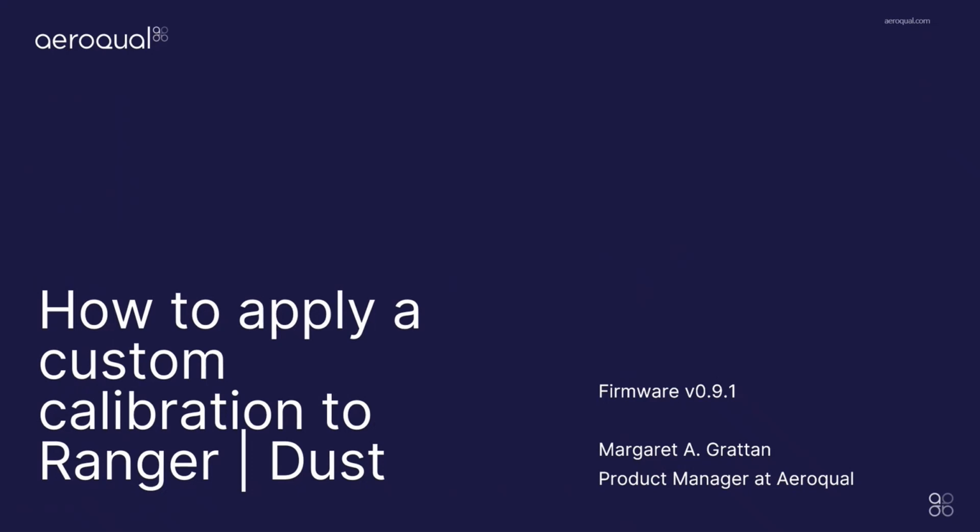Our topic is how to calibrate Ranger dusts using a custom calibration factor. The reason you'd want to use a custom calibration factor has to do with the fact that these instruments have been calibrated using ISO 12103, which is Arizona road dust. And all aerosols have different properties, which makes the readings slightly different. So if you wanted to improve the accuracy of your readings, you would want to apply a custom calibration factor.